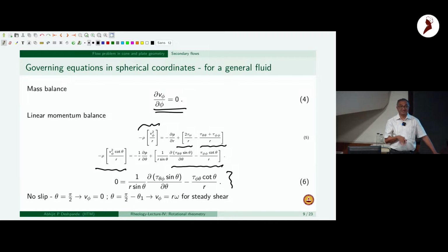So all of these go into our final estimation of the properties, and therefore the effect of angle is there. That's why generally we will have cones of one or two different angles, and if there is doubt about the quantitative nature of our measurements, we do measurements with both and try to see how much of an error there could be.